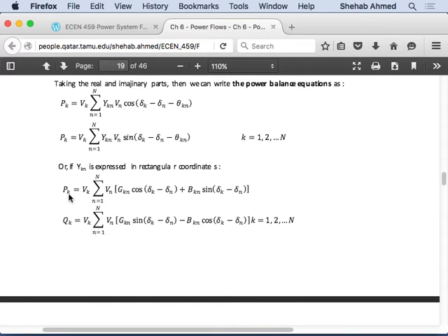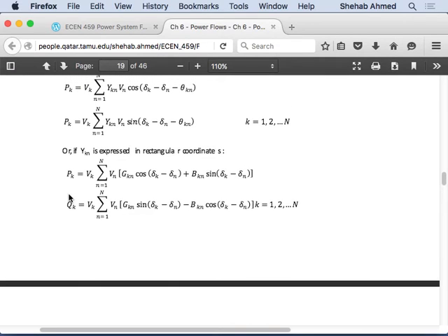So your variables are really not P, Q, and V and delta. These are sort of your unknowns in the system. But your states of the system, which are what you really need to calculate P and Q, are actually the V's and deltas. Right? Because if you know all the V's and deltas around the system, finish, I don't care, because I can calculate P's and Q's. Right? So does it make sense? Every bus, I can use these two equations. Unless it's a PV bus, I will only be able to use one equation. If it's a slack bus, I don't need any of the equations. Right?